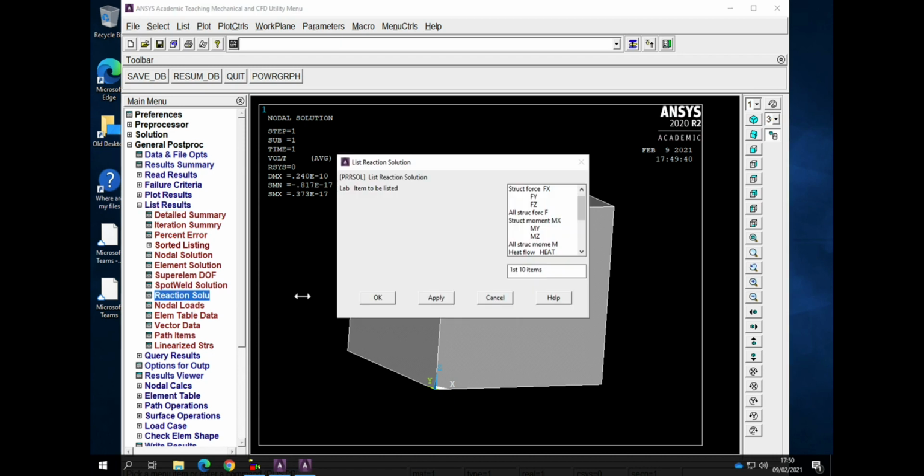So if you look at reaction solution, what you need is the corresponding charge that's generated. Now again, this is an artifact of ANSYS. It says amps here, but there's no real current because that has a time element, that's sort of dq/dt. But if you click on electric current, that actually provides the charge that's generated to maintain that constant 0 volts.